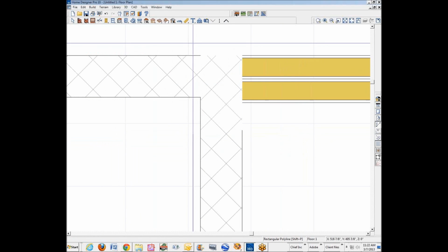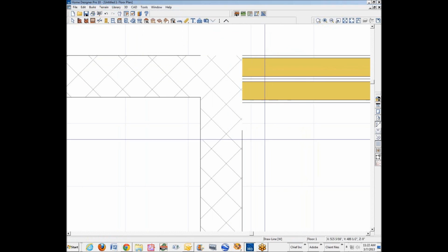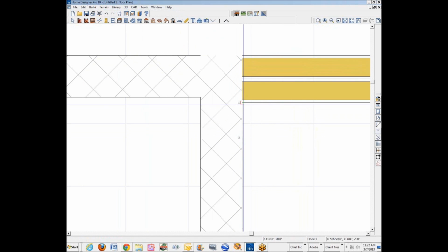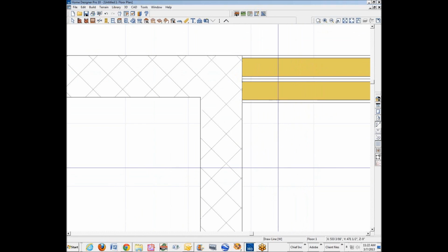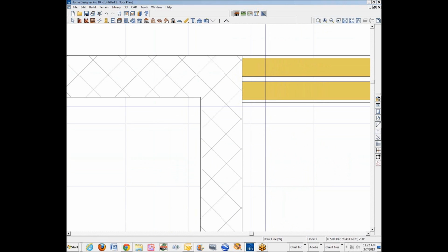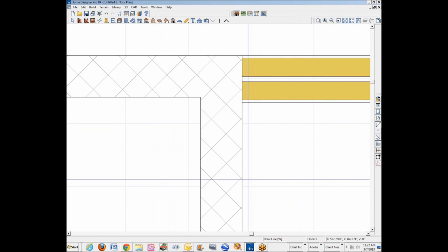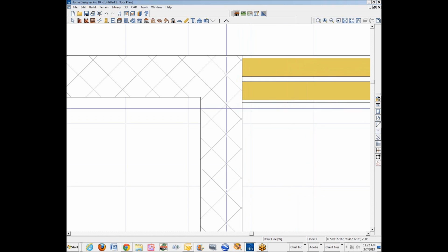Now it looks maybe better, but see, we lost this line here. I mean, there's all kinds of things you can do. If you want it perfect, you can make it apparently perfect. We'll go over here to the line tool and draw a line here, and then draw a line across here. That looks a little cleaner. And I guess you could take this line here and extend it, and that might clean it up a bit more. But if you want things to look perfect in plan view, you can make them that way by just what I'd call cheating. Or the old AutoCAD way, you just draw the lines and you draw a closed box and give it a fill. So that looks pretty good.